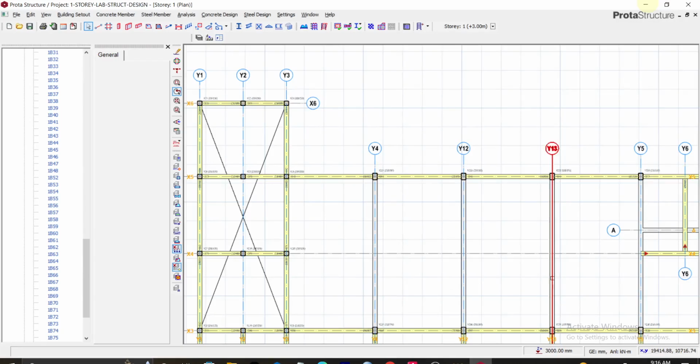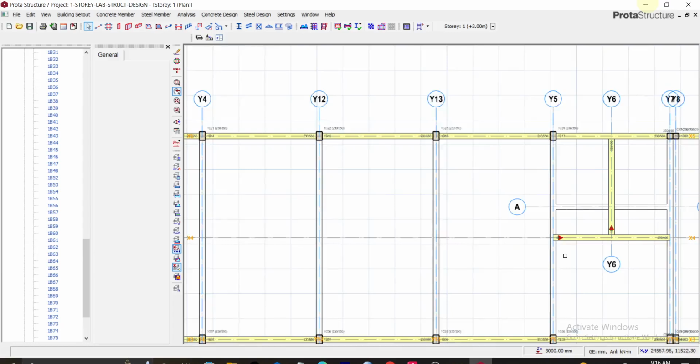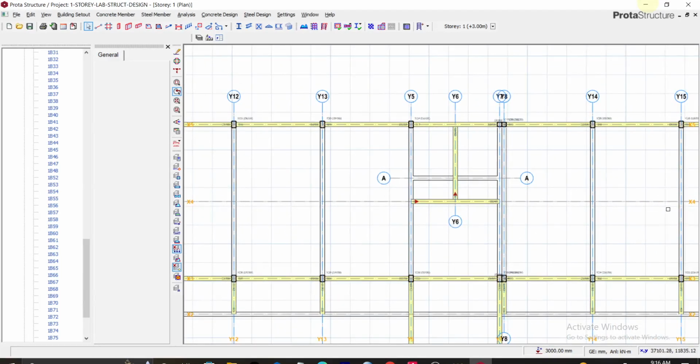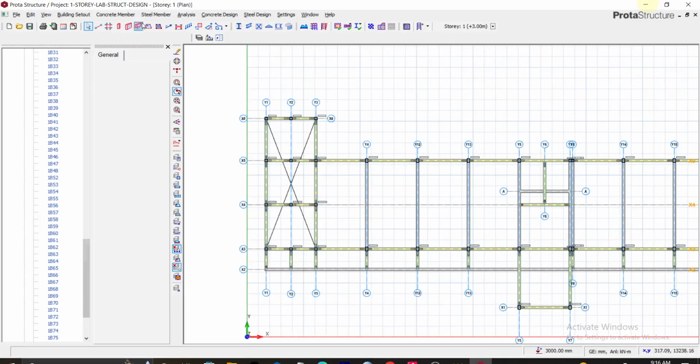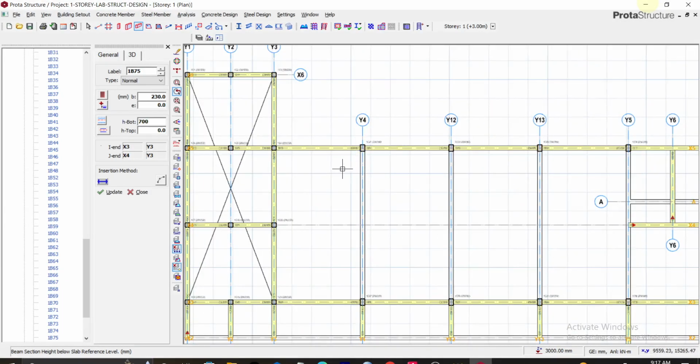So we are left with these longer spanning beams here that don't have a column. So for this one, I'll use a beam of 700. So I'll just simply come to here and change the breadth to 700. In case of failure, we'll see what we can do, because we don't have columns and these are very long. 8 span is a very long span. So this is like we'll be designing a bridge.